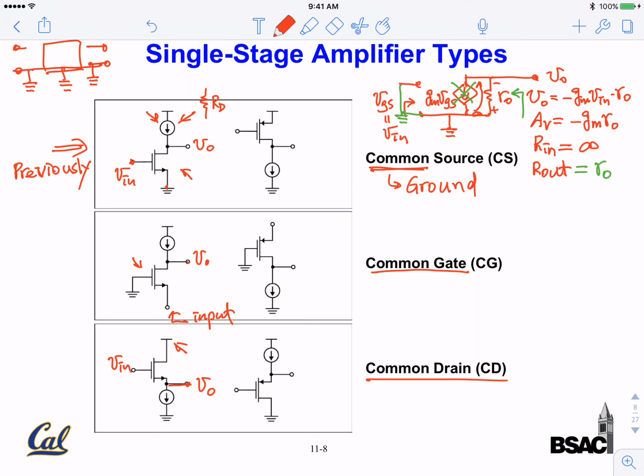This side is NMOS, okay, and PMOS is exactly the same, other than the source is connected to ground. Here, the source will be connected to the most positive voltage VDD. So, in other words, the whole thing is flipped upside down. And likewise, common gate: again, the gate is grounded, and the input will be fed into the source.